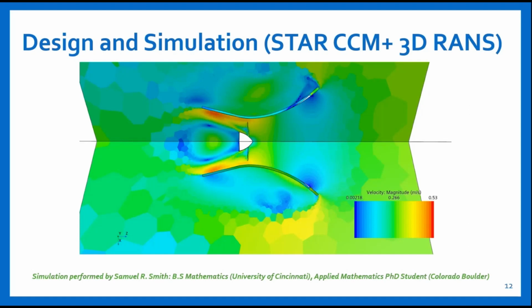For our design and simulation, we wanted to use COMSOL, but it turns out we didn't have the right package. So we decided to use STAR CCM Plus. It was a 3D Reynolds averaged Navier-Stokes simulation, which we solved over this duct, and we basically had an outer computational domain to simulate it being in a river.